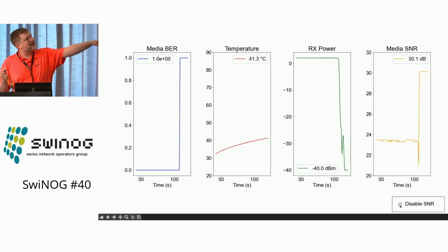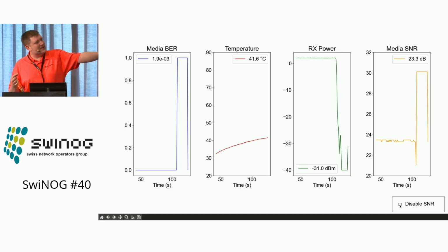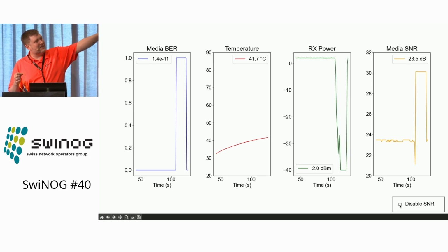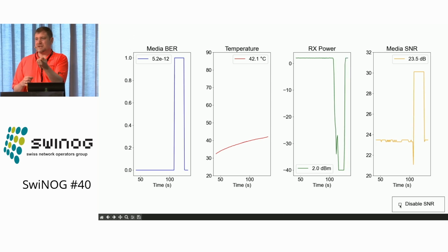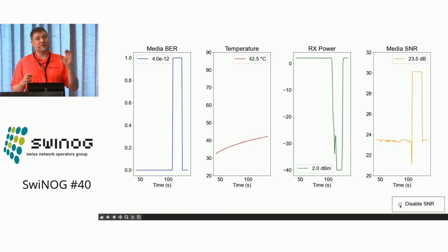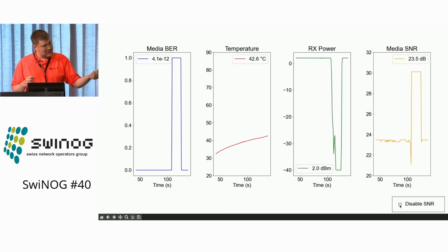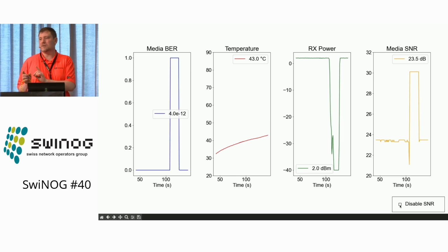It jumps up. And the SNR is also interesting. You don't want to go below 20. It almost went below 20. Then it jumped up, like the signal would be better. But as we learned in the previous presentation, SNR should be in a certain range. If it is beyond 30, it is bad, because we have the effect called shot noise or quantum noise.